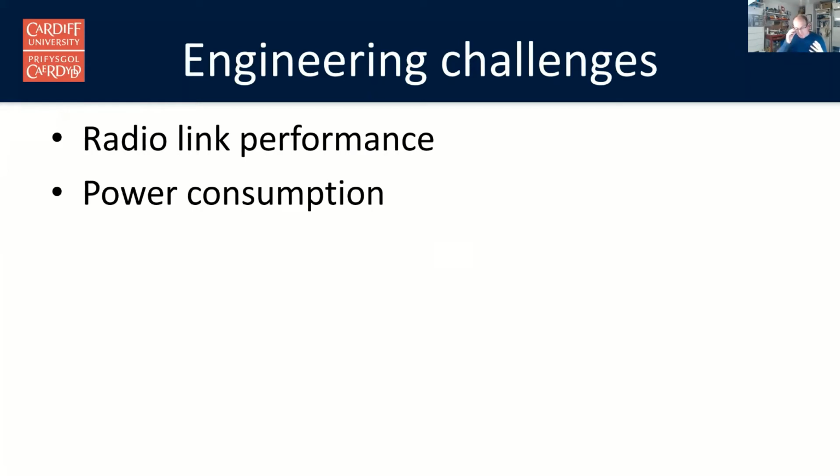And this clock circuit within the processor is used as an alarm, so that when it's time to make a measurement, it wakes up, turns on all the rest of the instrument, turns on the sensors, makes the measurements, encodes them into the right format, turns on the radio transmitter, sends the signal to the surface, then switches everything off again and sets the alarm. And whilst it's in sleep mode, it uses almost no power at all, because all it's running is just the quartz crystal to keep the clock running.